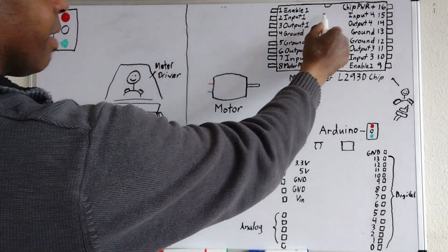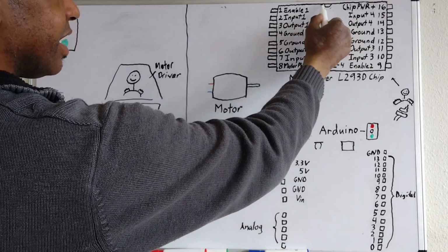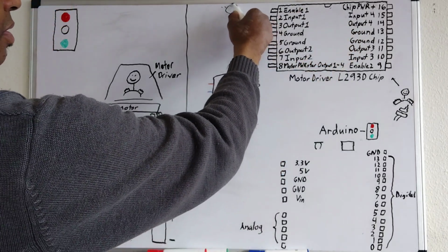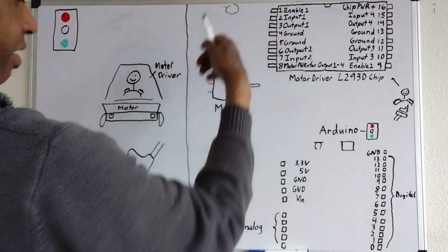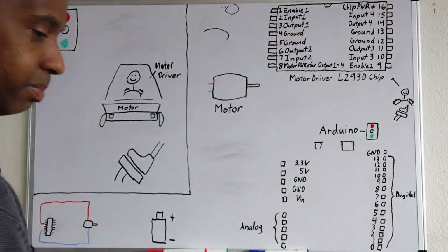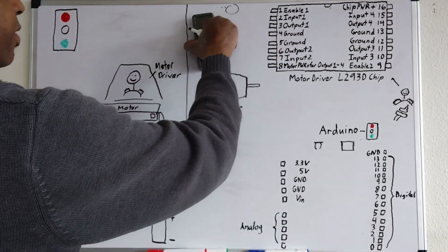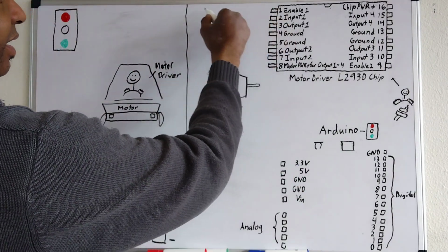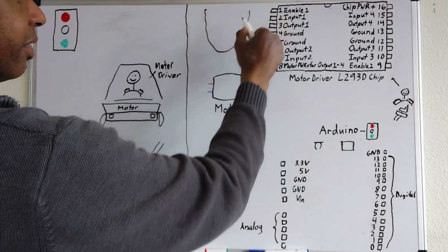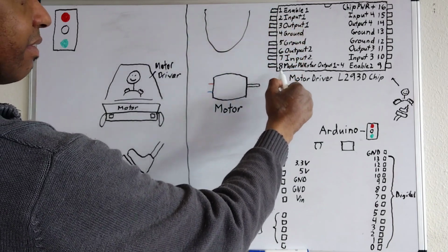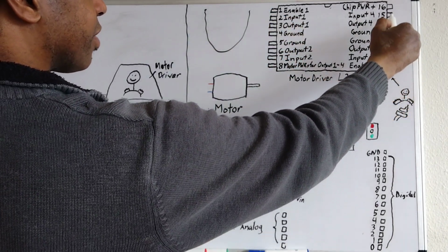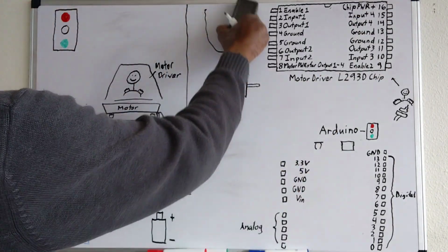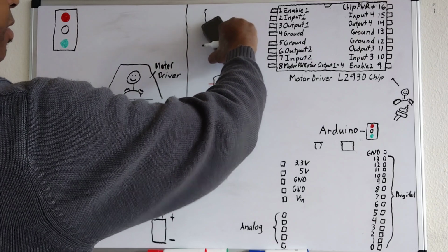Okay, so up here you have a little indenture, it's a smile. Always put that up there, you know, have it smiling. Never a frown, that's bad. Always a smile. Okay, and then when you count like a smile, like you would draw a smile. 1, 2, 3, 4, 5, 6, 7, 8, 9, 10, 11, 12, 13, 14, 15, 16, up. Okay, so that's how the pins are numbered.